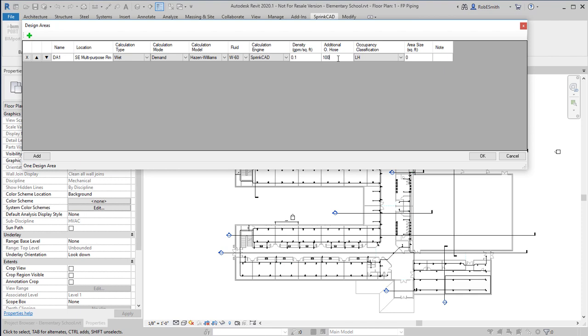So even if there are no hoses on site, even if there are no hydrants within the envelope of the fire protection system that we're calculating, again, between the source point and the flowing sprinkler heads, if the nearest hose outlet is a hydrant beyond the scope of our building, this additional outside hose will act as a reduction to the power of the source point. And that is all according to NFPA 13 requirements.